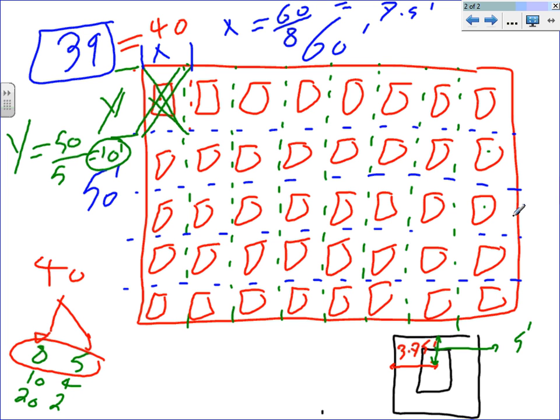That would work. But at least this, if you know the number of fixtures, will give you a good calculation. Visual also has a little component where, if your room is a rectangle or square, it will do the layout for you. Really nice. It does the layout and then you drop it on the CAD. I'll show you how to do that. But how does Visual do it? Most likely, it always tries to keep the number of columns and number of rows as close to each other as practical. Okay, so that's basically what I want to talk about on this one. Any questions, guys, about laying out, finding the average, and laying out the fixtures?